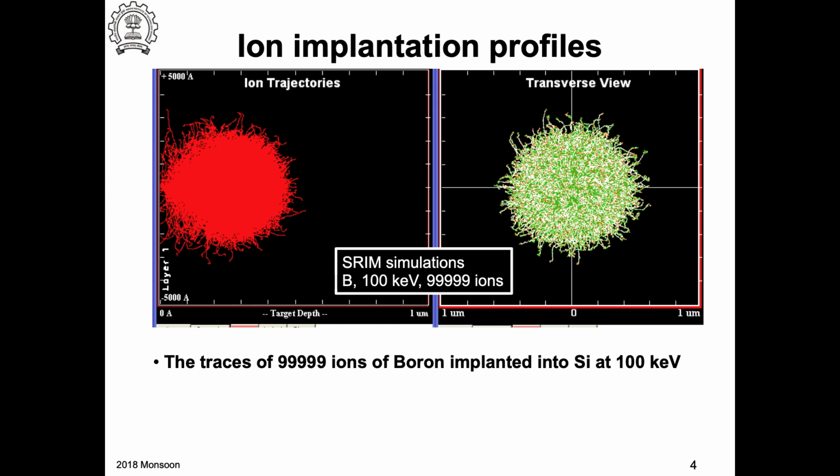You can see this thing has been studied quite extensively. This is actually called variability, device variability. Anything about very small devices, you need to worry about variability. So if I'm making an extremely small MOSFET, there are dopant fluctuations. First of all, the number of dopants in the channel and source drain are not the same for every device. As a consequence, the characteristics of these devices would vary a lot more than a 1 micron technology device, because you are talking about a dopant being there or not. You can't say that half a dopant is there. That's not possible. So this is a problem. This is a very dramatic example, but I think it conveys the message. So this is one source of variability.